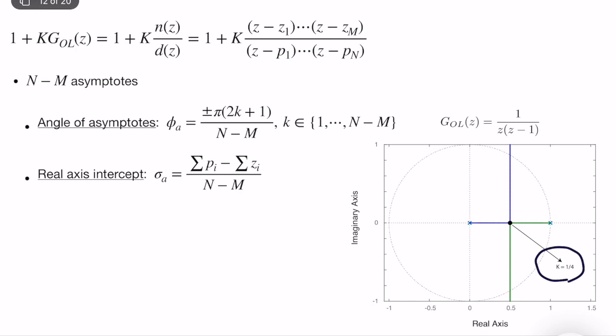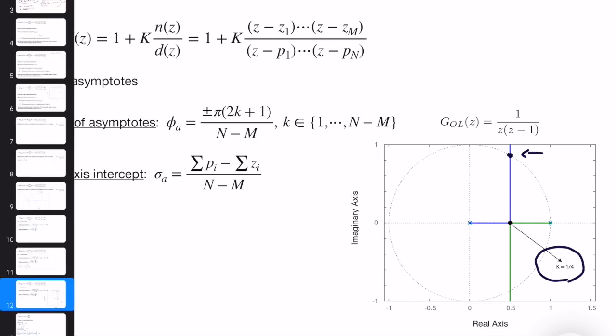It really qualitatively changes the behavior, because here, until you hit the breakaway point, you have two real poles. They are both positive, which means that there are no oscillations. And after that, you start observing oscillations, and of course, there's overshoot and other kinds of details. And at some point, you become unstable. Computation of this by hand is much messier than computation of imaginary axis crossing in continuous time systems. Okay, that's good. So let's go to breakaway and break-in points.